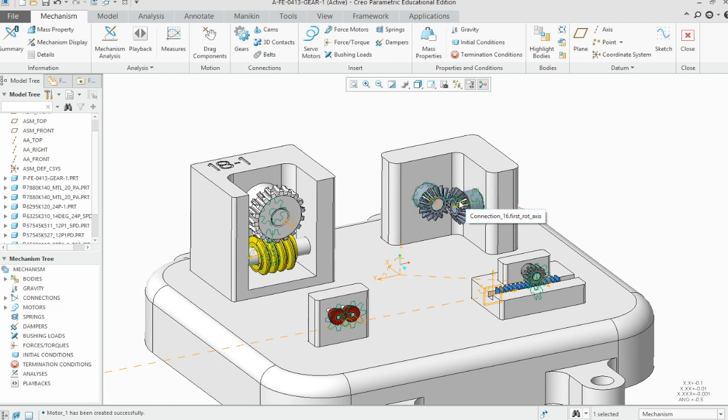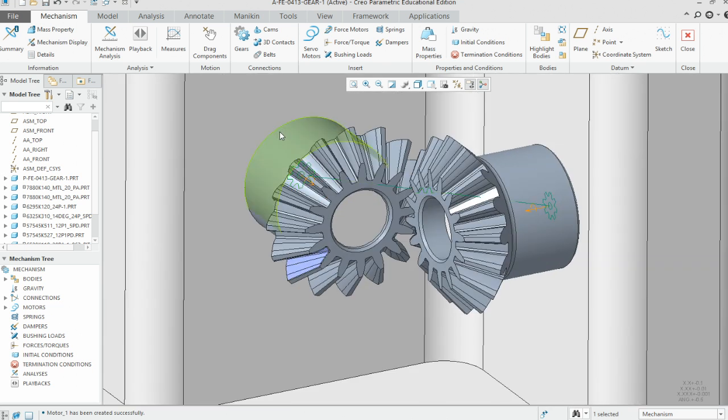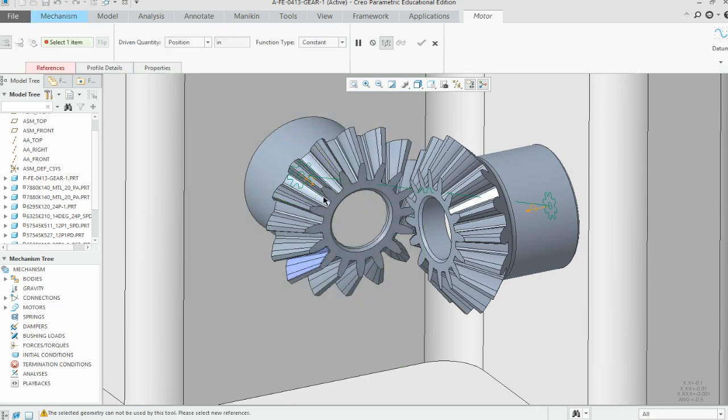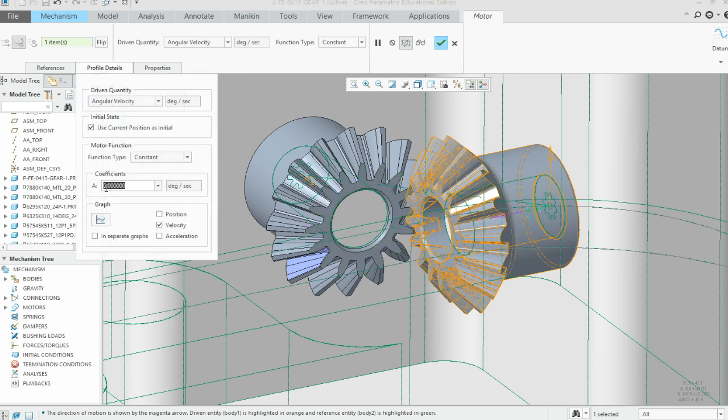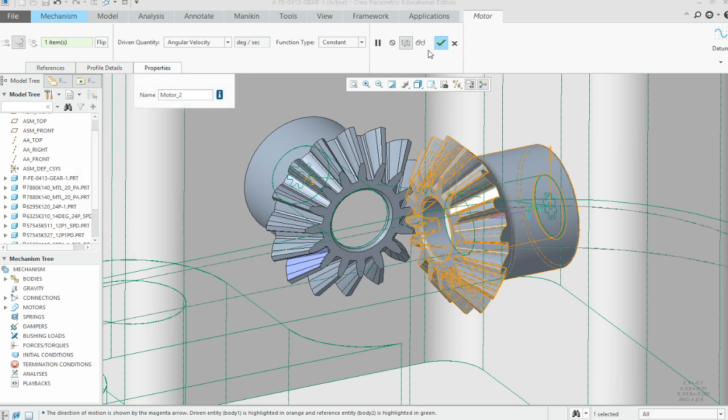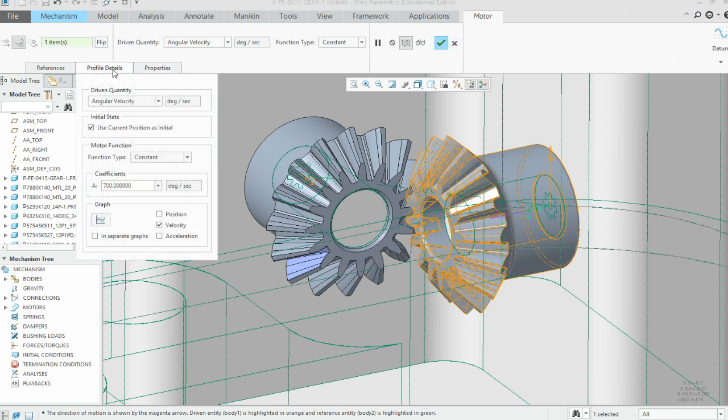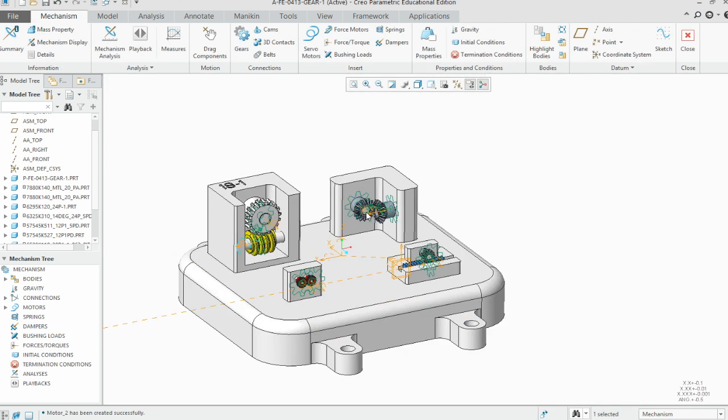So let's now do that operation over here for the gear, and we'll put in another servo. Off this servo right here, we'll put it into location. We can see that it is turning clockwise. So clockwise it's turning. It's going to go angular velocity, and then that angular velocity will say 700 again, because it's roughly the same size as the other one. So we want them to have a good set. Touch somewhere else once you've entered that, either hit enter or go back up, then you'll get the green arrow.